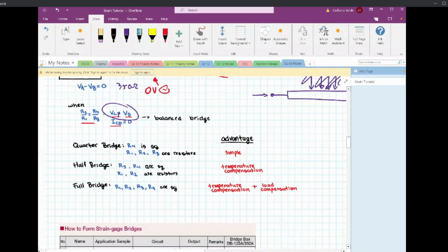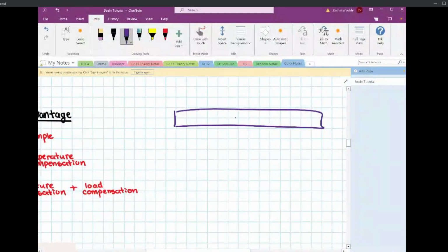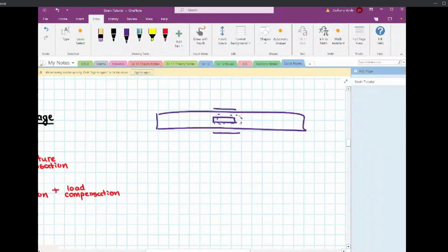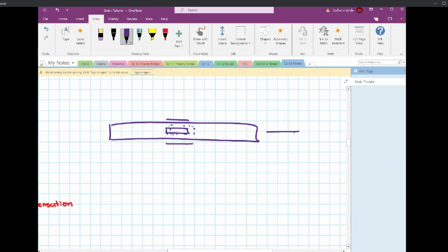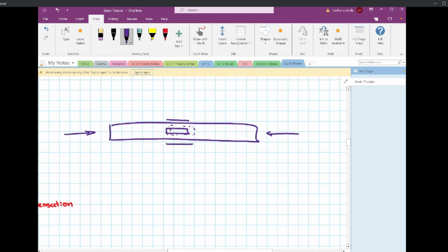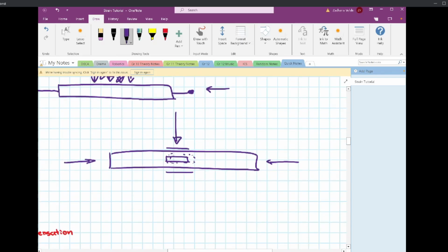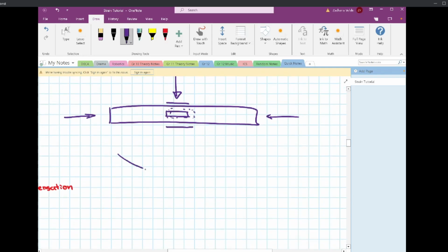The way it looks, and this helped me visualize it, is that you have strain gauges on all four sides. When you experience that compressive load going inwards, all four strain gauges see the same compressive load, because they're all being deformed inwards by the same amount. But when bending comes in, the strain gauges at the top get stretched out.